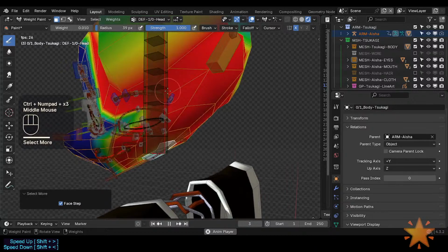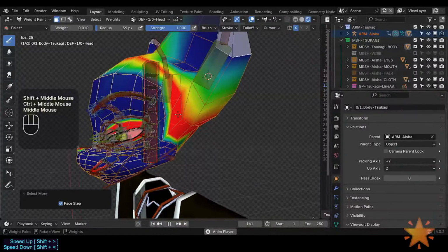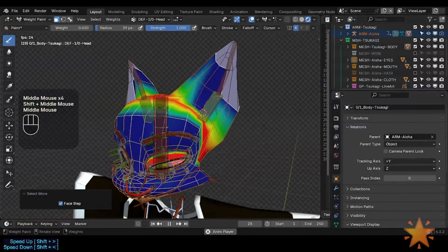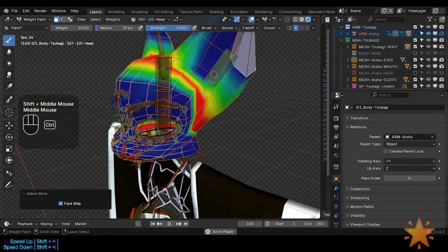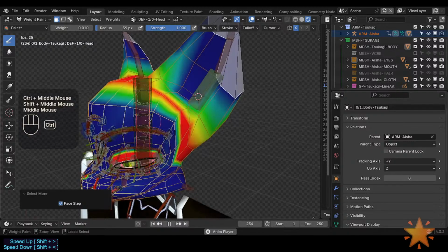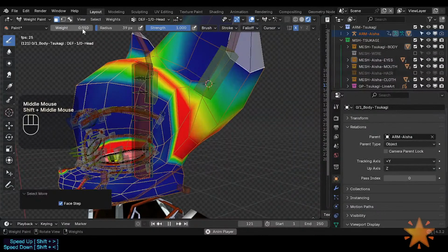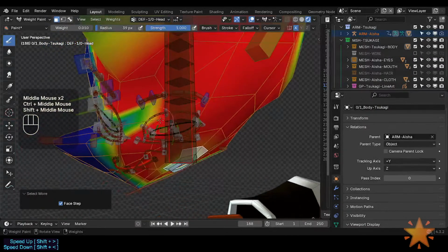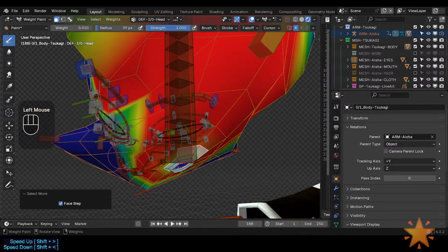And probably the skull here behind the neck and on the sides, under the ear, all this will be more skull rigid, right? The ears are not, so this is why they are. I have made the mask before to take off the weights, but not sufficient to take all of them. So at least the head will have generic values. I use 0.001 here, but here I'm using 0.10, so it doesn't really matter. It's slow weights. There is some regularity, and so here I'm gonna do the same thing.